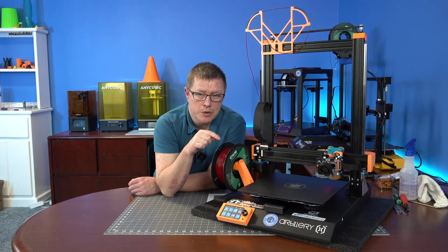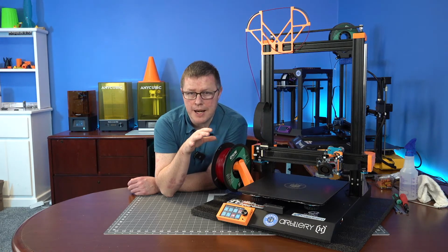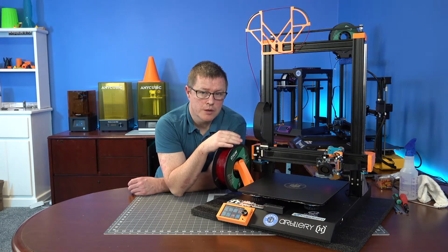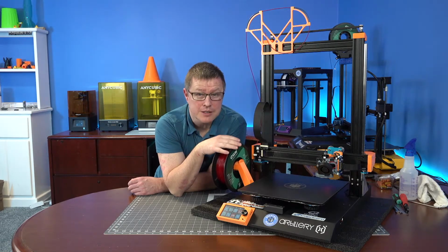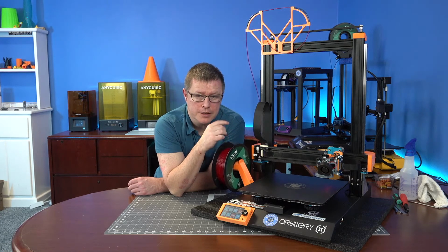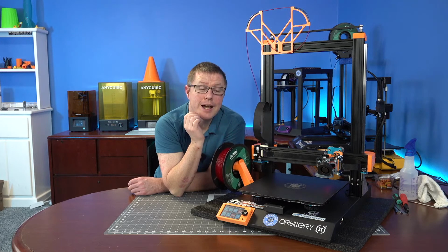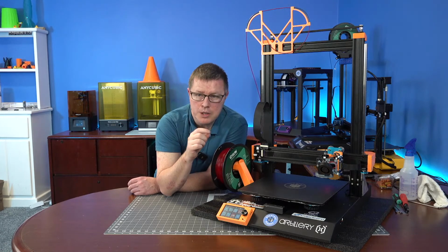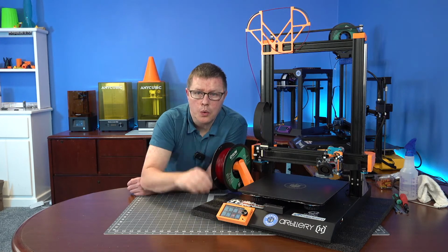But the way I'm doing the tuning is a manual way, but it's kind of half between automatic and manual, because there is no way to use an accelerometer right now to tune it for Marlin like you can in Klipper. I'm hoping in the future they figure that out, because I've been messing with it for a good couple of weeks on my SP5 Core XY 3D printer, and it is a unholy pain in the rear. But I'm working on a way to simplify it, to just punch in some numbers and it spits out numbers for you. And hopefully have a tool on my website that works for people to use.